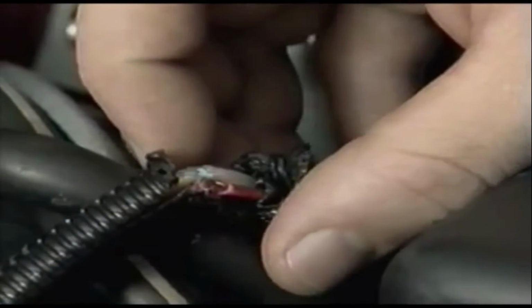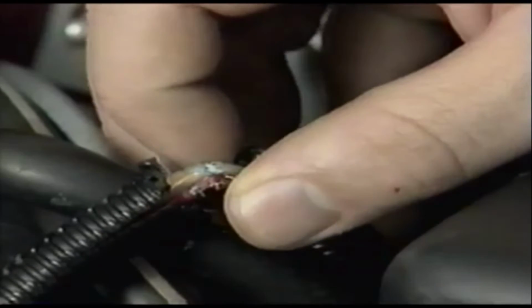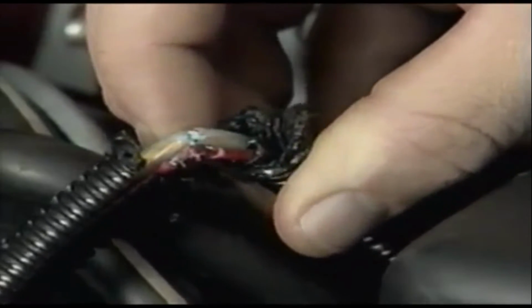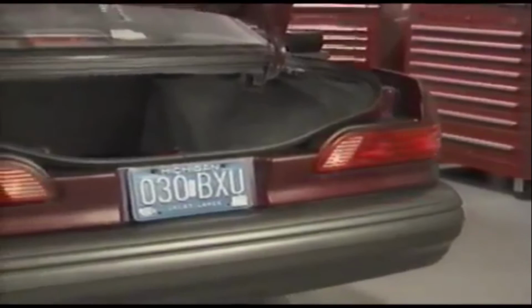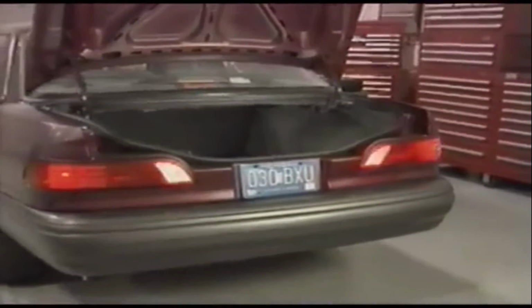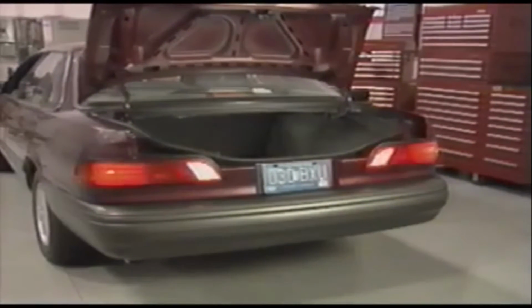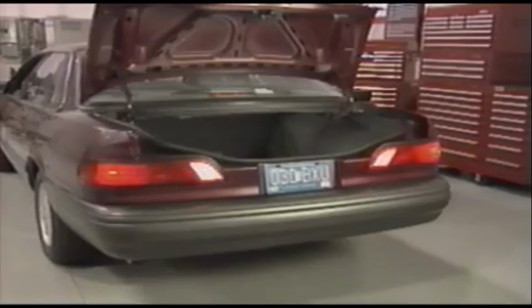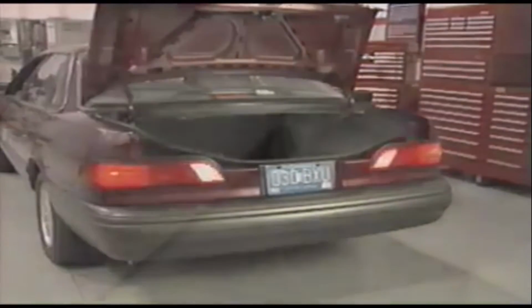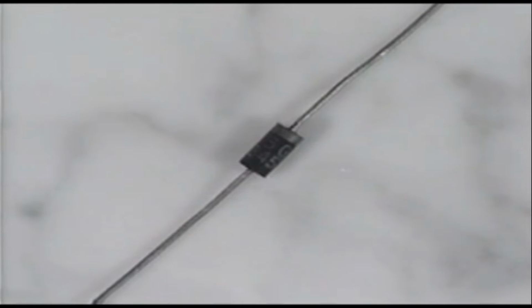Wire-to-wire shorts result from damage done to the circuit by an outside source. In a wire-to-wire short, current is allowed to take an unintended path or backfeed through different components. The fuse for the circuit remains intact, and signs that something is wrong are usually components not working right or working when they shouldn't. At times, feedback voltage or spikes are experienced in some electronic circuits.